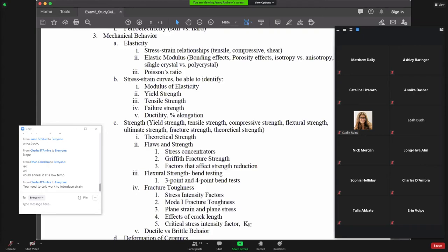I think it's diffusion for that. No. Does anybody know what's the driving force for grain growth? So the driving force always is going to minimize energy of something, right? So if your grains grow, what energy are we minimizing? Grain boundary energy. Yeah. So as our grains grow, we have less grain boundary area in our sample and we lower the energy that way. So diffusion is more of a mechanism by which it occurs, but it's not the driving force.